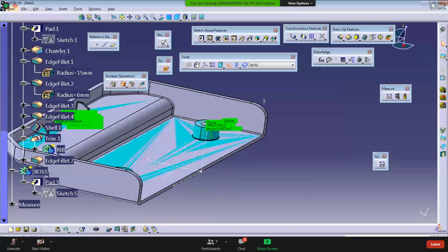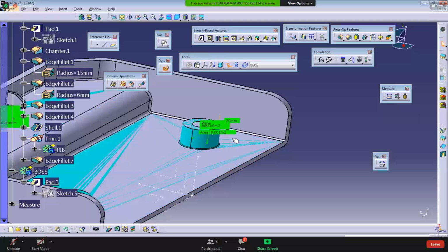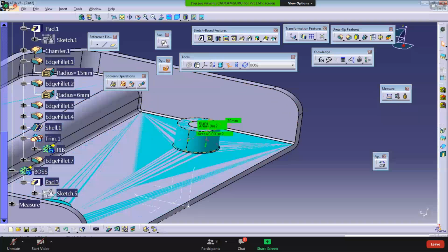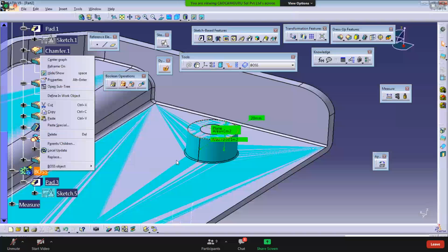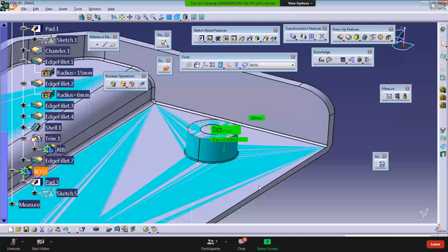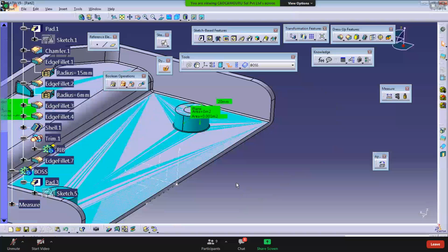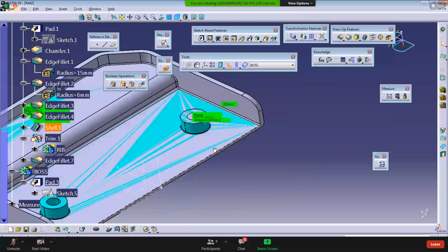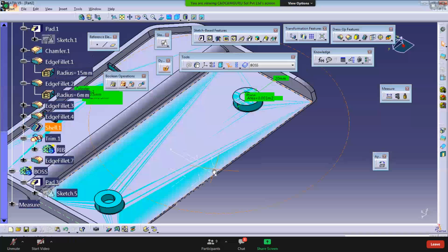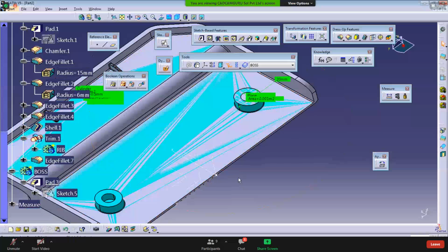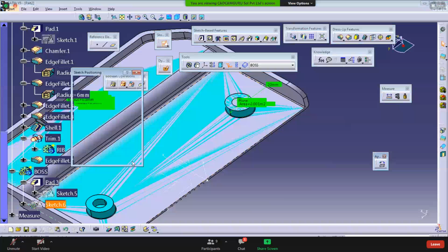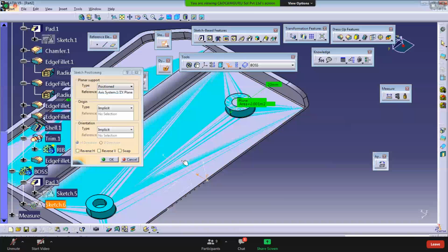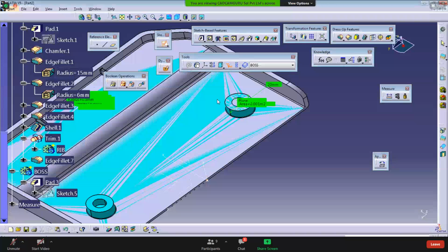Okay, now there is a hole inside it, but before the hole there is a tapered shape. So how can we achieve that? Just see. Take this, or you can go to the sketch. First introduce the plane in the reverse direction.